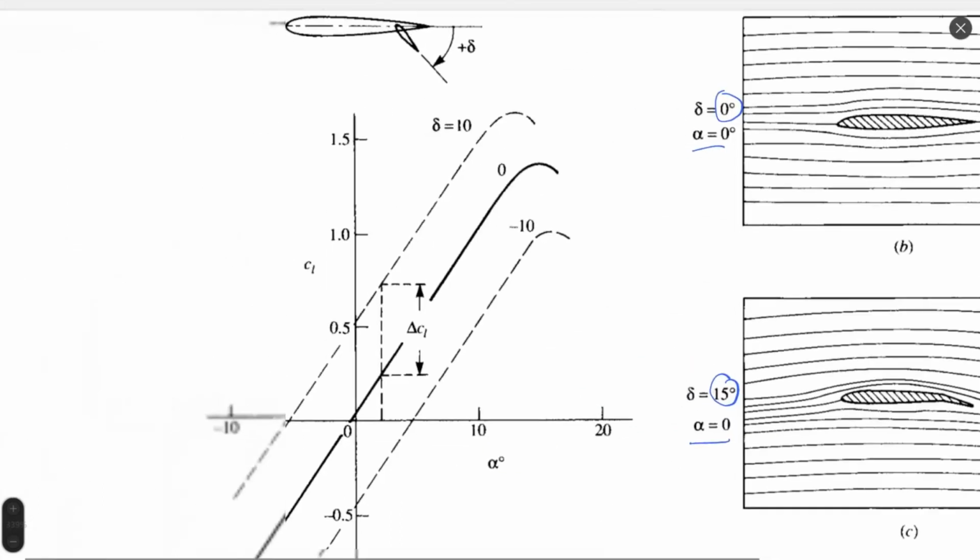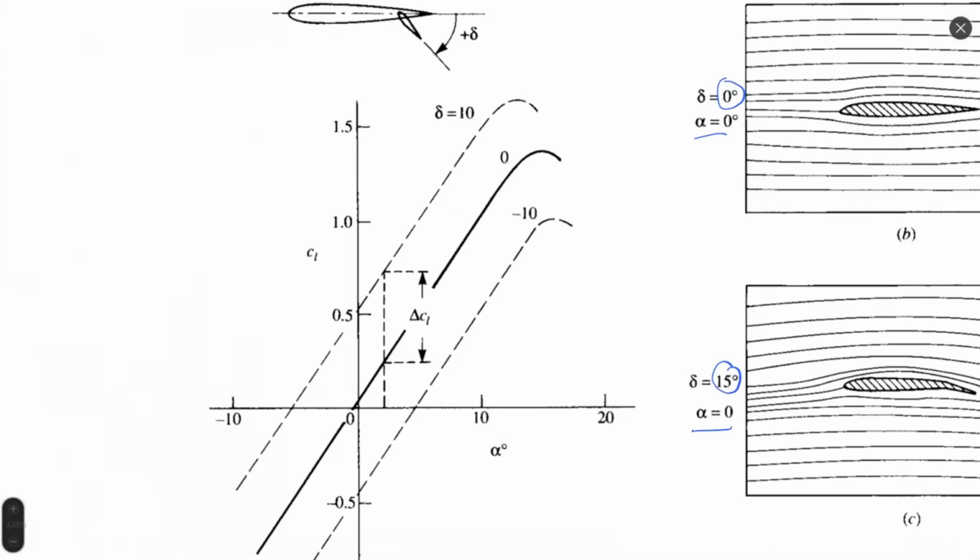If we look to lift to angle of attack plot, we will see that for positive inclination of flap, we gain positive effect on lift coefficient, can be in order of plus 0.5 lift coefficient, but it also depends on size of flap.